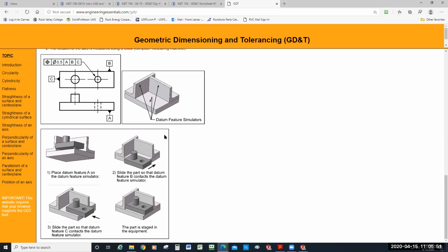Right. There's a rule of thumb that an engineer at Sunstrand told me a long time ago, that the drill is going to deviate off its center by 2 times the diameter of the drill over the depth. 2 times the diameter? Yep, 2 times the diameter of the drill. I said, oh, really? It seems excessive, and I think it might depend upon the size of the drill too.